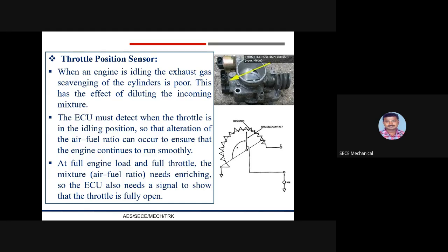In the potentiometric type sensors, a multi-finger metal brush is in contact with the resistive strip. While the butterfly valve is turned from the lower mechanical stop to WOT, there is a change in the resistance, and this change in resistance is given as the input to the ECU. Non-contact type TPS work on the principle of Hall effect, inductive sensors or magnetoresistive technologies, wherein generally the magnet or inductive loop is the dynamic part, which is mounted on the butterfly valve throttle spindle shaft gear, and the sensor and signal processing circuit board is mounted within the ETC gearbox cover, and it is stationary.